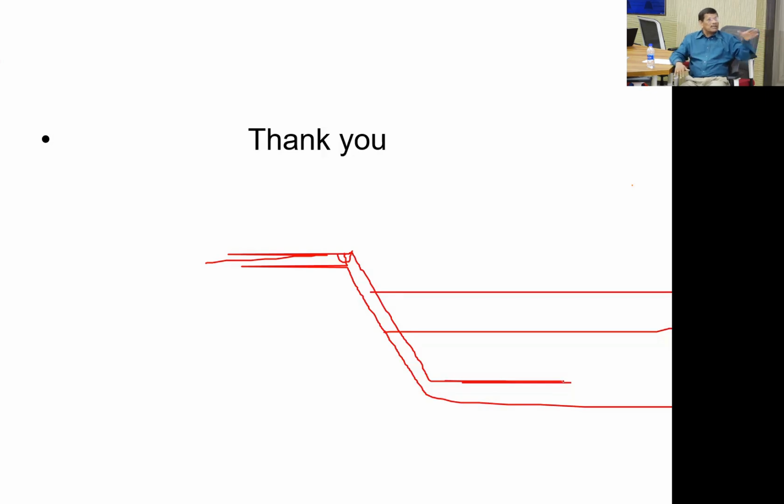That's why normally we do not go anything steeper than 3 to 1, because on the slope you cannot go there. Installing on a 3 to 1 slope is difficult. You cannot do any test, so you just leave it and assume that it is all good. You are using so much material and you cannot test it once you put it there. You can only test on the top or a little bit on the bottom.